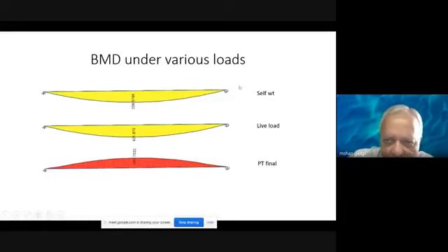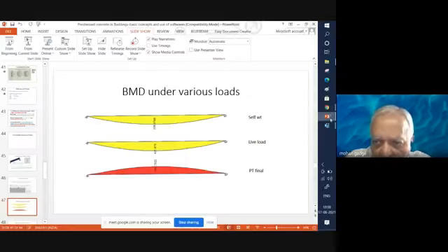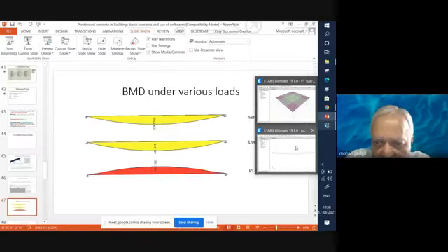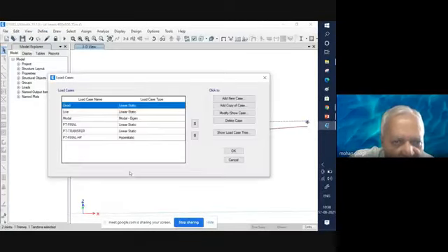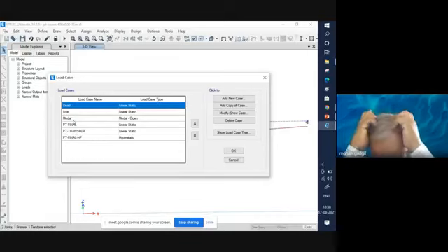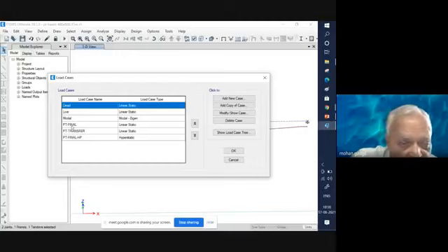Now I have got the self-weight bending moment. There are different loading cases; I think I just forgot to tell you. For this beam we have the loading cases as dead load and live load. The modal load we are not much interested in, because our objective is to consider the analysis for dead load only, and dead load plus live load. Then we have this pre-stress force.